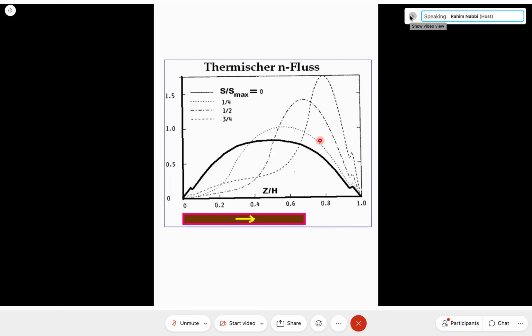That means the flux distribution inside the reactor at the initial phase of an operational cycle gets such a shape. You see, the maximum is at the lower part of the reactor. With the operation of a reactor, of course, the fuel is consumed because of fission process, absorption process, and so on. That means the control rods have to be partially removed from the reactor core.